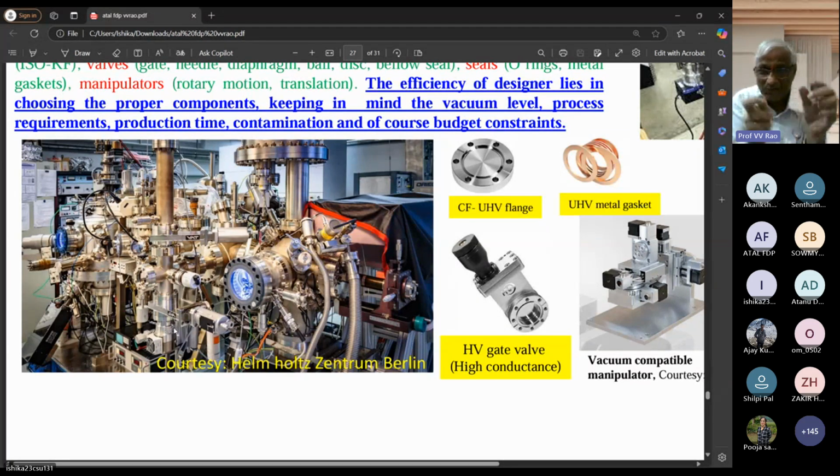There are flanges with bolt and nut. Those are ConFlat flanges. They will be sealed by the metal gaskets. There are small KF couplings with the O-rings. When to use O-ring, when to use flexible bellows, when to use what type of walls. So many components and central chamber.